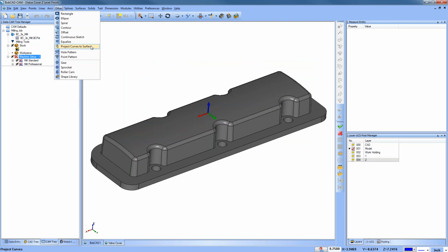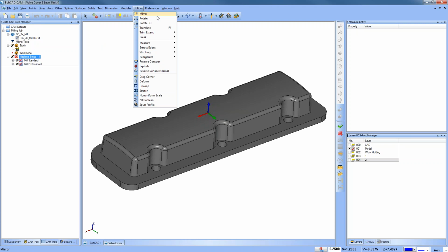I make molds. How do I engrave in reverse? How can that be done? That is a great question, Glenn. Give me your email address, Glenn, and I'll send you a video that shows exactly how to do it. I think I did it on a mill turn one, and there's another video. But if you need to inverse the text, just use mirror. You can do utilities mirror, that will mirror the text, and then you can send that along and use it for your engraving.